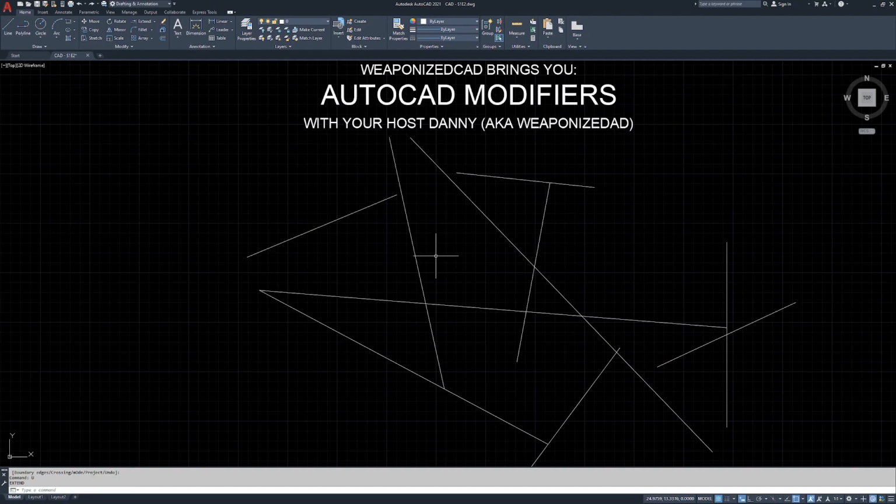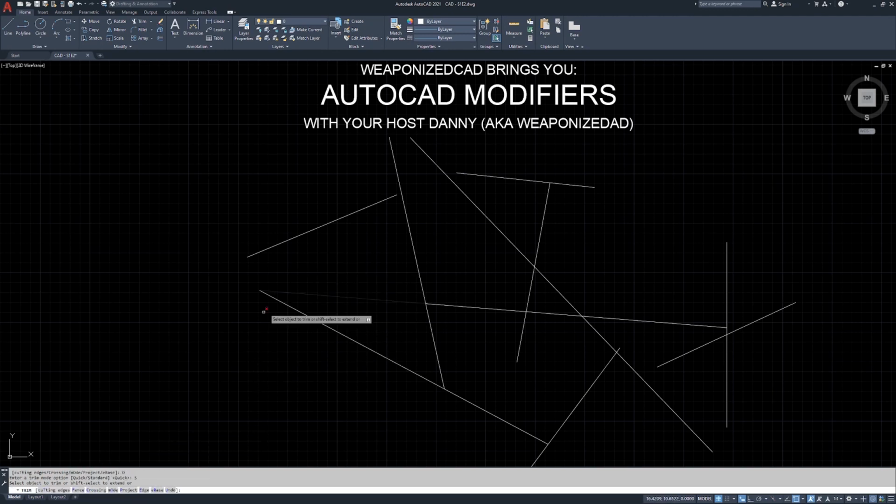So when I was explaining the mode selection in the trim command and the extend command, it gave us two options. It gave us quick extend and quick trim, and it gave us standard extend and standard trim. Now, the way that I work, let's go back to the trim command. Click that drop down arrow up in the panel. We're going to go to trim. I'm going to click mode. I'm going to actually set it to standard down here. What this lets me do is it gives you a little bit more control over what you're trimming.